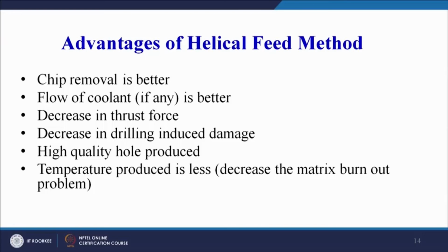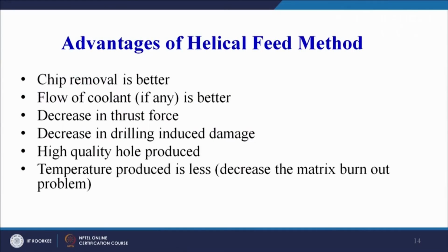As I have already explained, there is a decrease in the thrust force, and therefore a decrease in the drilling induced damage. So when the force decreases, in almost 99% of cases your damage will also be less. Quality of the hole produced is good and the temperature produced is less. So the matrix burning is less and there is less heat buildup in the machining zone during the drilling of polymer matrix composites.